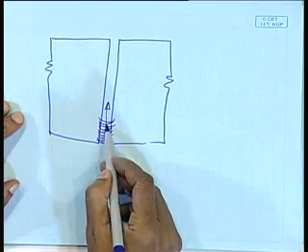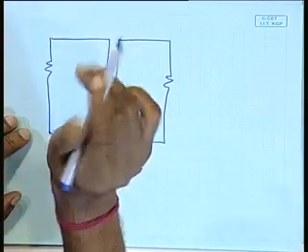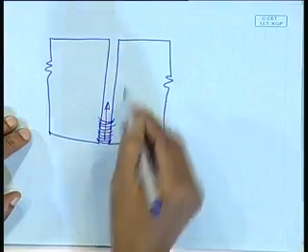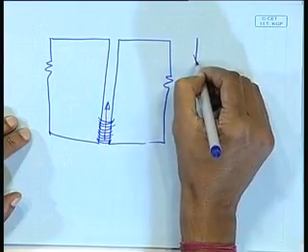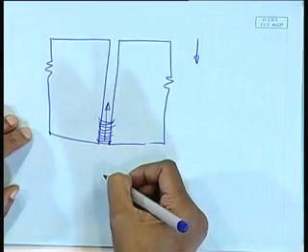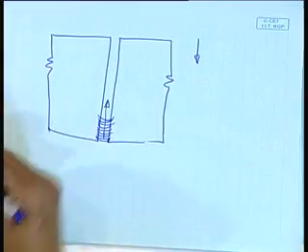This solidified metal itself is providing me support. The metal is getting transferred and getting support from the solidified metal below. But when I am coming down from the top, that is a different thing. The molten metal will tend to fall off because there is no support below.